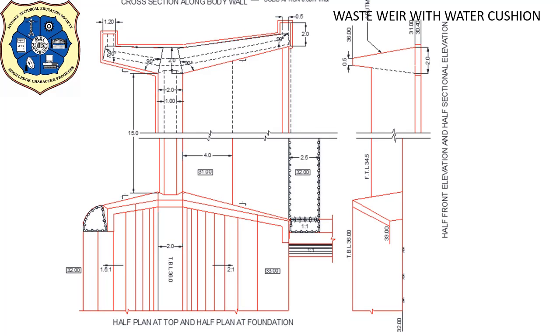Then join whatever projected line here, from this point to this point. Show guide bund portion by giving side slopes 1:1. This is the guide bund. This is optional. It is not given in the details. Just we are assuming and drawing the details. This portion can be projected here. Complete drawing by drawing the sloping lines of earthen bund, which is slope of 2:1. You have to mention here 2:1 slope that we can observe when we look in this direction.